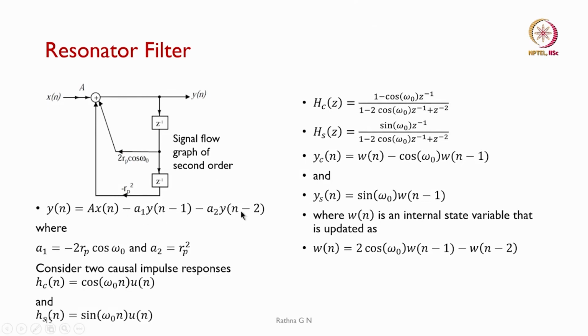So, with this IIR filter with 2 feedback, we can calculate the amplitude with 2 inputs, because it is an LTI system. Usually we give initial conditions 0, then by giving x of n equal to 1, it automatically starts resonating, and then we can generate different sine frequencies and use it in our sine generation.